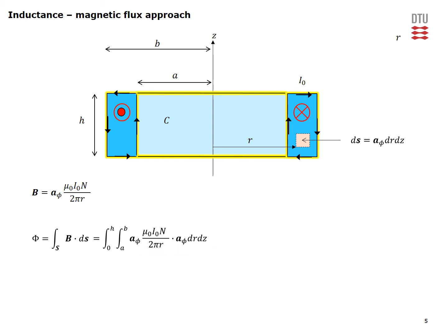Phi dot phi is unity, and here what we have to do is essentially integrate 1 over R function. This is constant in Z, so our integral in Z will actually just amount to the multiplication with h, and the integral in R will simply be ln of R, and after you insert the limits, this is our final result for the magnetic flux inside the non-magnetic core.